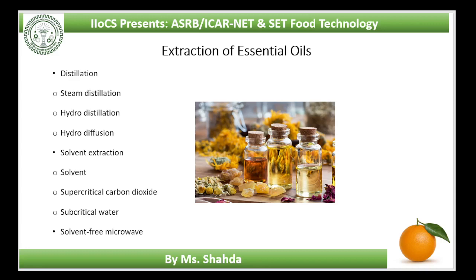Subcritical water. Subcritical water, or pressurized hot water, has been introduced as an extractant under dynamic conditions, with pressure high enough to maintain water in a liquid state and temperature in the range of 100 to 374 degrees Celsius. The efficacy, in terms of essential oil per 1 gram of plant, of continuous subcritical water extraction was 5.1 times